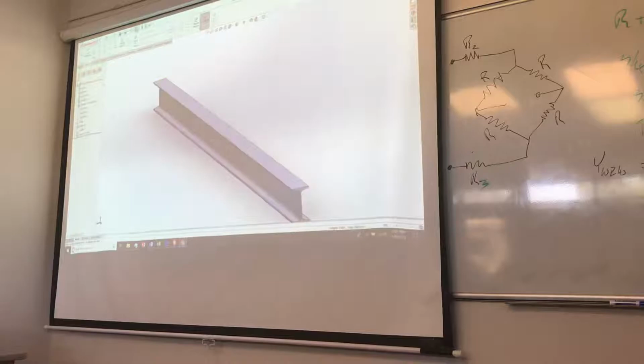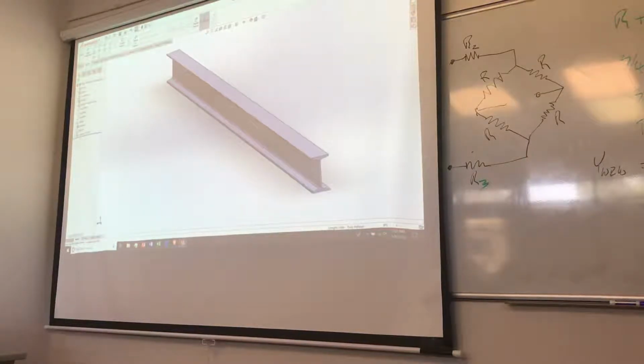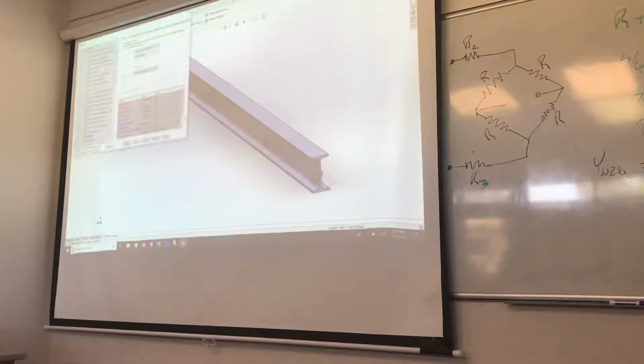Okay, so I'm going to say okay. I've got an S section here. I like my S section. It's actually cool. Okay, so now I've got a perfectly fine section here. I'm going to go do the simulation, new steady. I'm going to go beam me up. Okay. And now we're going to go, of course, define some material to this. And because I don't know any better, I'm going to say it's A36.